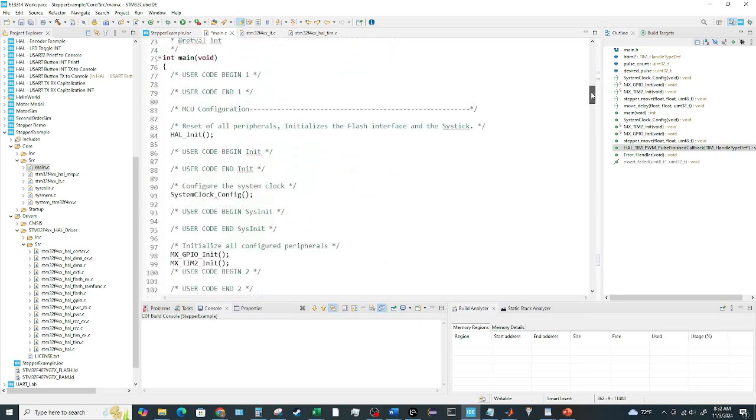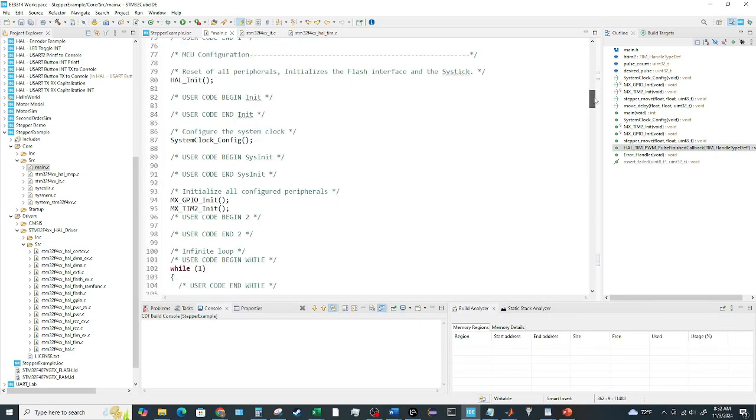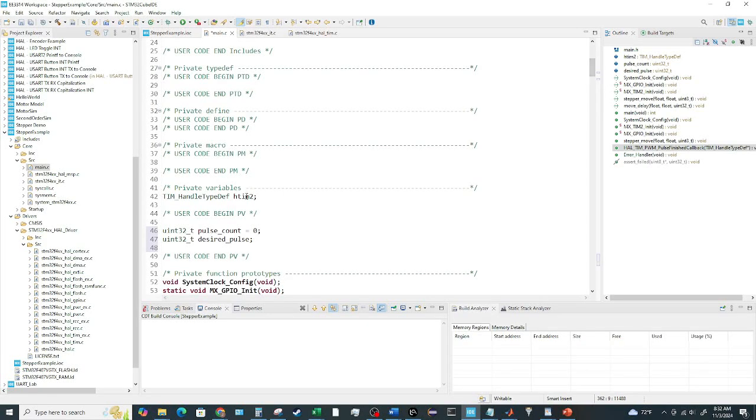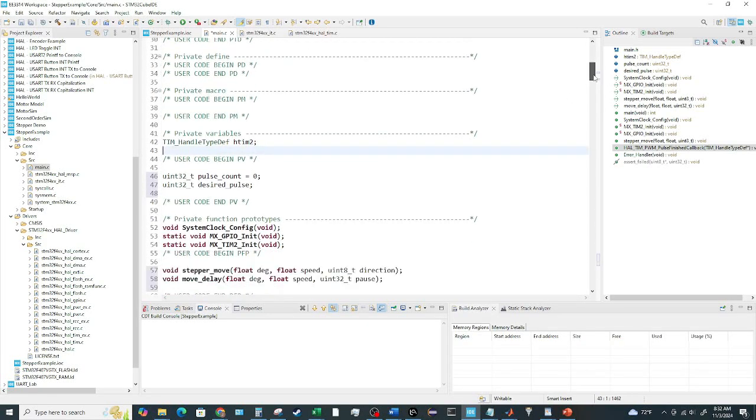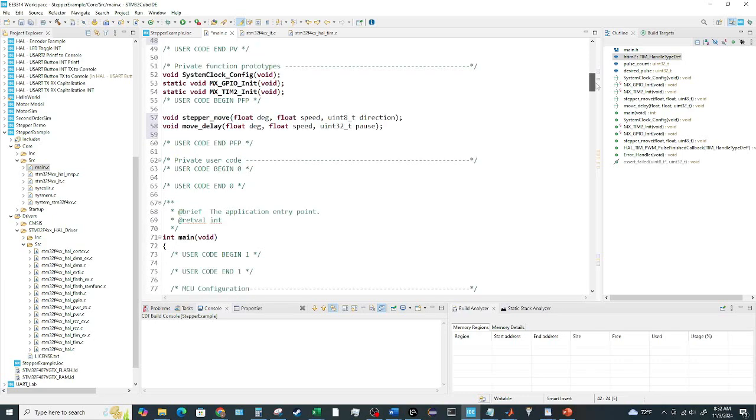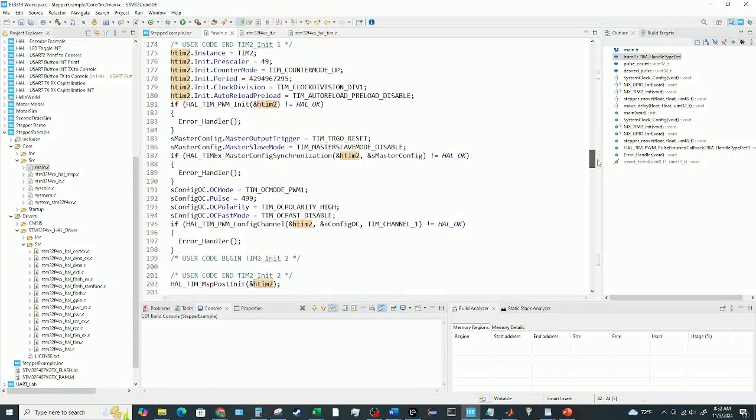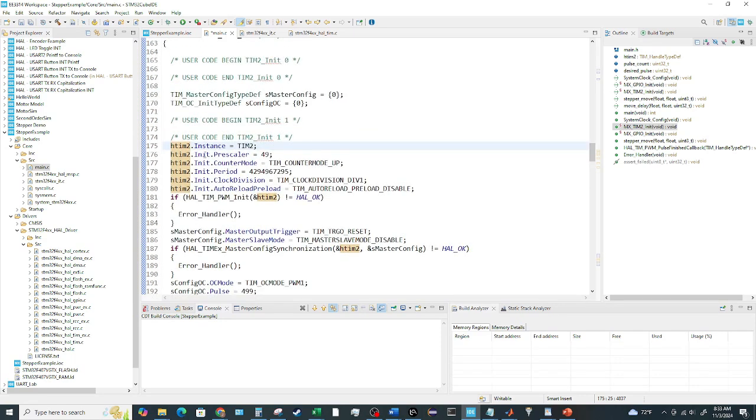So we define htimer2 right here, and then we populate that structure. That actually exists in memory. If you look up where that variable is in memory, it's going to be a certain location in RAM. When we populate the structure, it's a structure in RAM, and we're assigning numbers to all these different member elements. So htimer2, this whole structure, is going to be the address of the whole handle, right?